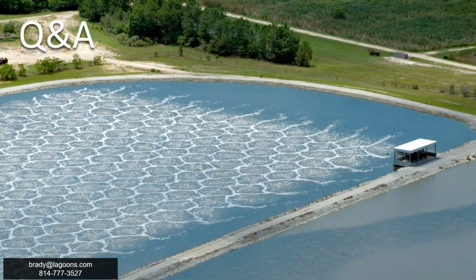Another member asked about phosphorus removal. That's a different conversation, obviously, than energy efficiency, but we recommend flocking it out with some kind of coagulant or flocculant, settling it out in the lagoon system, or depending on your limit, removing it with some kind of device, whether it's a sand filter or a disc filter. In general, mechanical removal is the best way to go. BioP is very difficult to get reliably for low limits from a phosphorus removal standpoint.